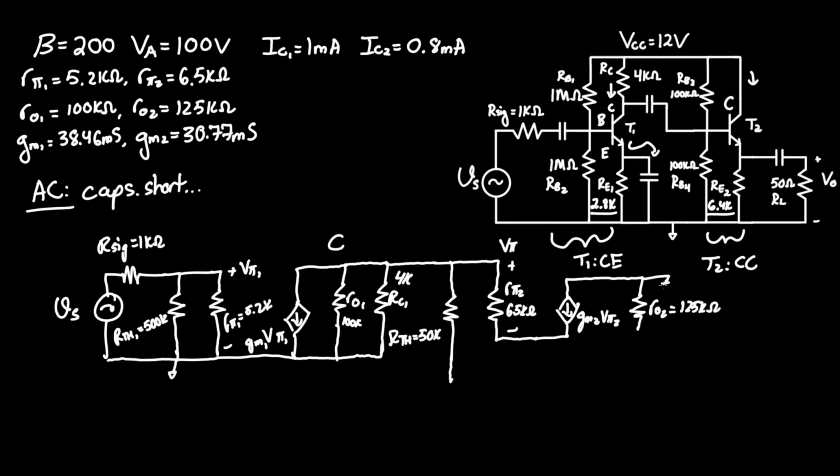And keep in mind that the top is grounded since 12 volts is a non-oscillating potential. However, we do have to connect the bottom here for the emitter. And since this is the pi equivalent model, it looks a little weird, but we now have to connect RE2, which is down here, which shares the same bottom potential as our Thevenin, or just ground.